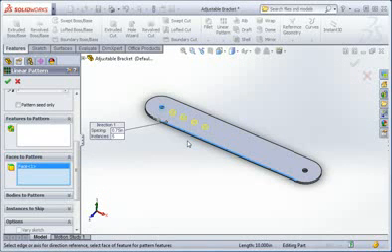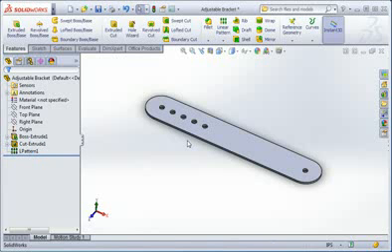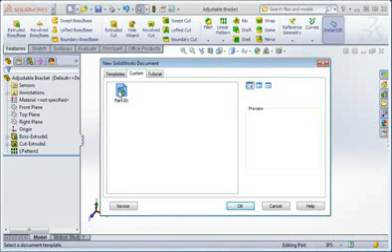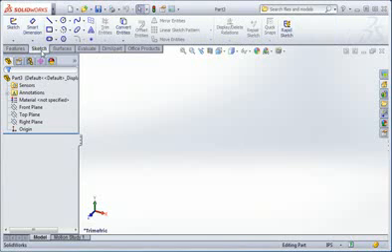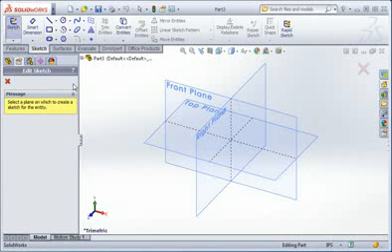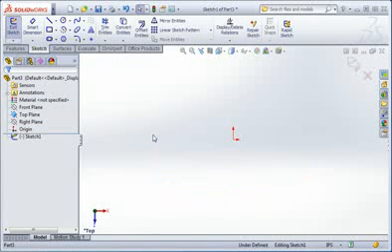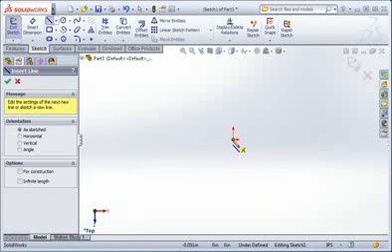But as I said earlier, if the part was more complicated, we could not use this option. You'll see why in just a minute. Type the Enter key to create the pattern, and then save the file. Now let's quickly create a new part so that you can see how face patterns work. Create a sketch on the top plane, and then draw this profile.